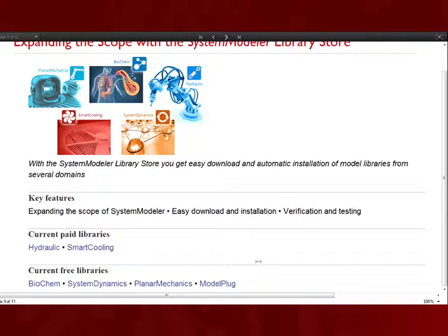Can you use each Modelica library? Okay, so I guess the question is if you can use all the Modelica libraries. There are a lot of Modelica libraries out there. In principle, the answer is yes. But the real answer, I have to admit, is no, because there are many Modelica libraries that are not completely complying to Modelica. They have, for instance, Dymola-specific code still, so they have some cleanup to do. And many are outdated, old versions that we're not supporting, so those won't work either. So there are some restrictions, but in principle, yes, you can use others.